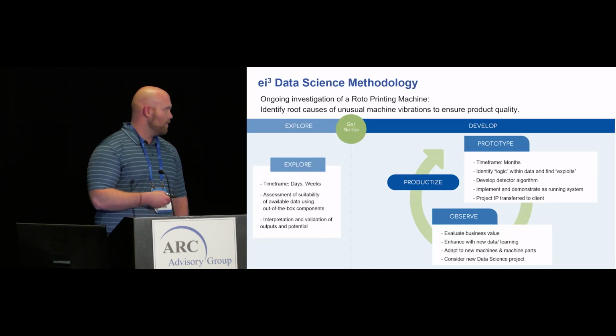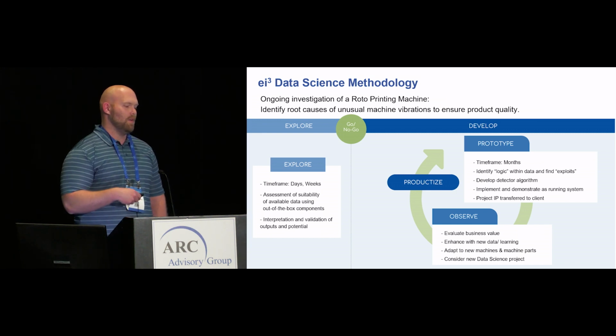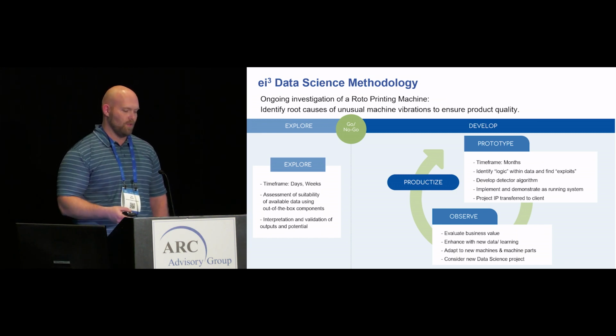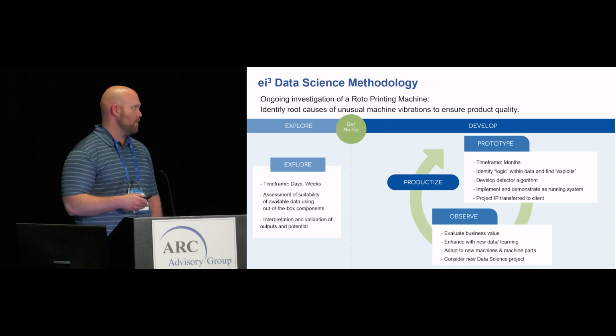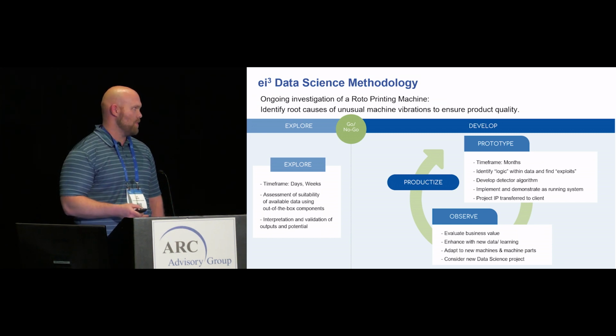So this is the model that we're essentially using for that predictive analysis. We did the Explore. We had a monitor put on. We looked at some potential issues. They did a characterization of the machine when it was believed to be healthy, assessed if they can see potential problems, and then we took it further, installing the sensors on multiple machines in the same location.